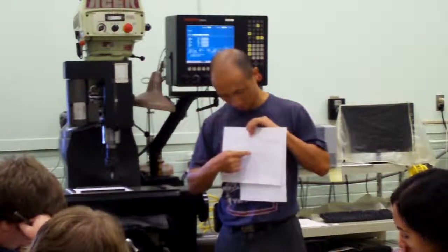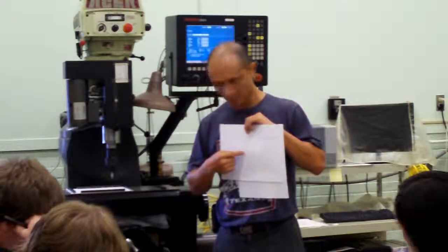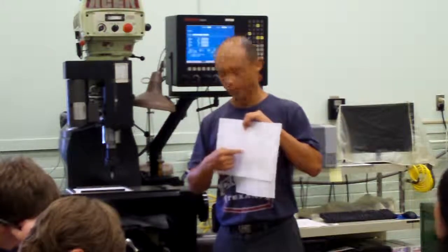What does that mean? I'm going to move from the current position by 0.5 inches to the left, in the negative X direction. So right now I'm here, I move 0.5 inches to the left to draw this line. Then the next line is Y 0.5, therefore I just move 0.5 inches up in the positive Y. Then I have positive X 0.5, negative Y 0.5. Okay, so I finished the window.